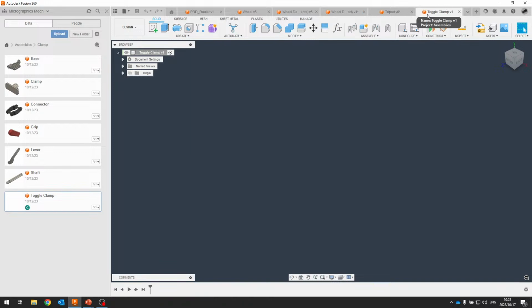The other method for distributed design would allow you to take an empty design. It has to be saved with a file name so that Fusion can link the designs, and you would take components that are already designed up. So I'm going to grab these tutorial components from Fusion. There's a base here. I want to insert that base. You can either drag and drop, or you can right click and choose to insert into current design.